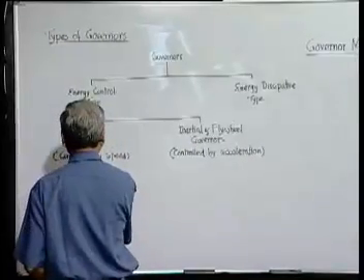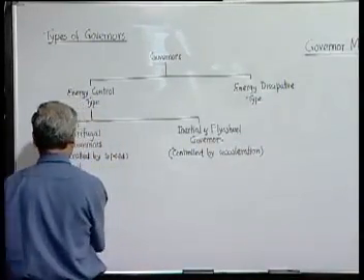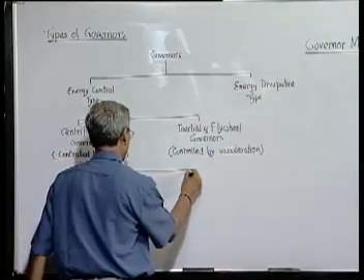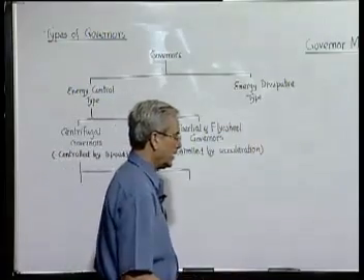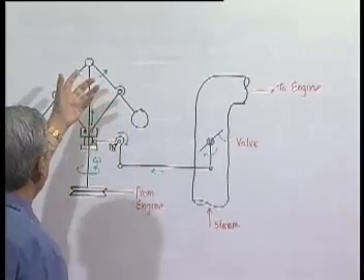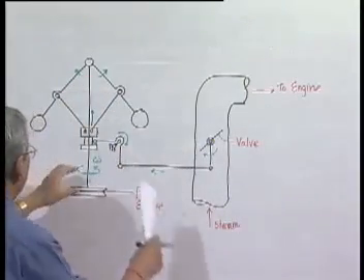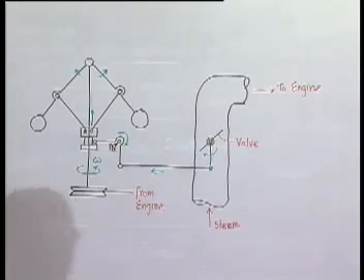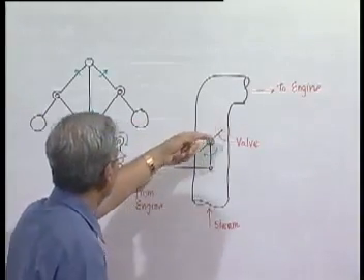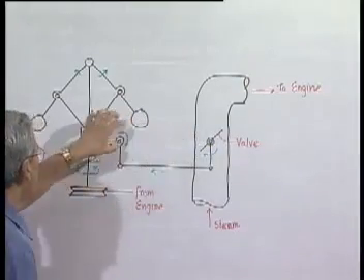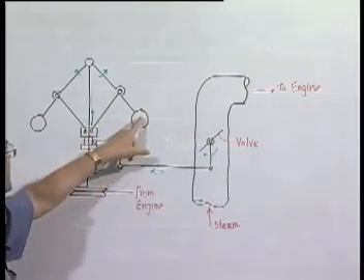Now here again, these types of governors are further classified depending on their control, that means their restoration mechanism. Here, what actually tells this governor to come back, or this ball to come down and take the sleeve below if the speed reduces? It is mainly that the deflecting force, the centrifugal force, is being balanced by some restoration, which is nothing but gravity.